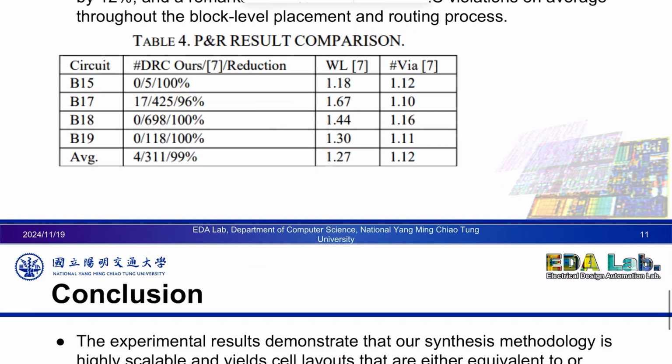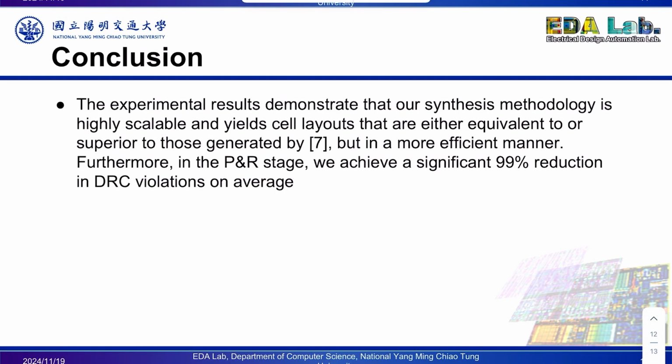Okay. The conclusion is we demonstrate that our synthesis methodology is highly scalable, and we can have the same quality or even better quality compared with the state-of-the-art. And our proposed DRC-aware RPA method can help us achieve 99% reduction in DRC violations in the PNR stage.